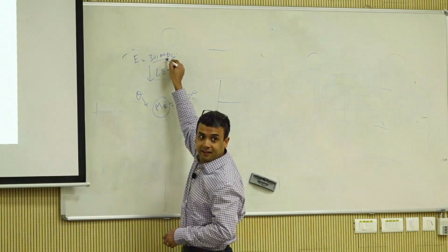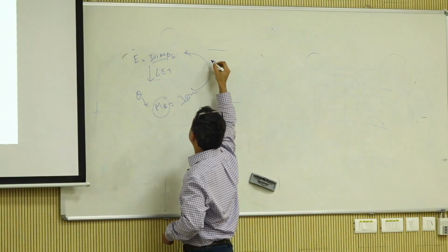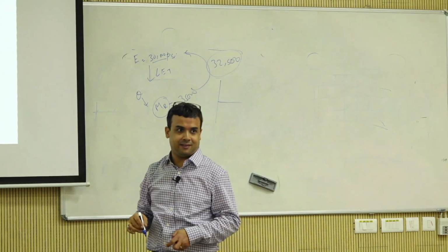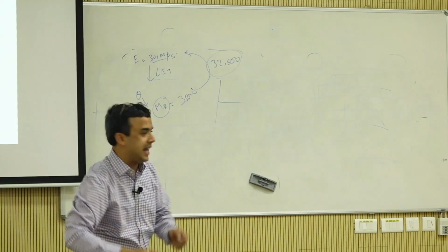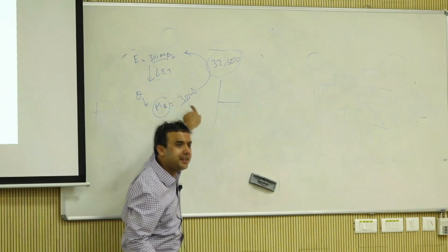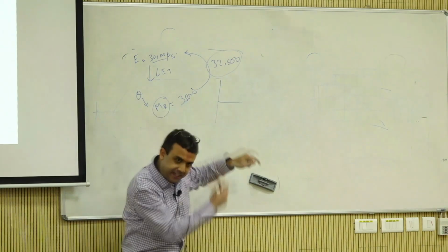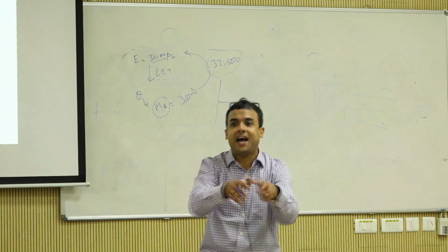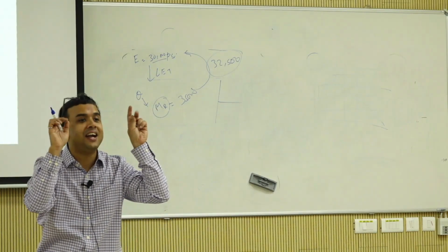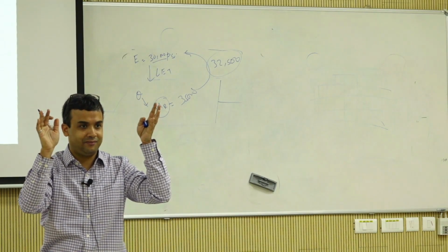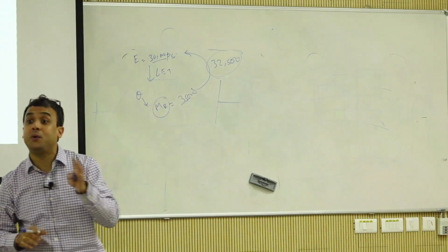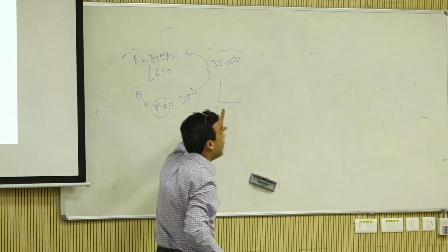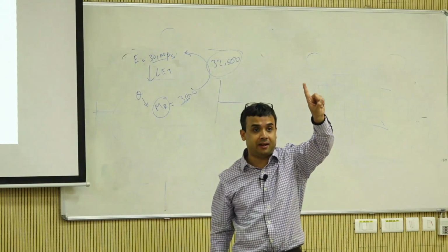I started at 30, so I rerun this with a value of 32,500, which is the midpoint of the two. Then I again calculate theta. Then I again calculate resilient modulus. Then there is a difference. I take the average again. I again run it until I converge. Then I know this is my right representative modulus value. This is what you are doing in LET, layered elastic theory, because you are assigning only one modulus per layer.